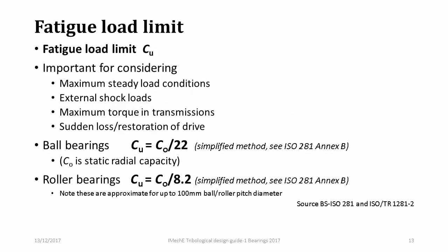Fatigue load limit. Even with all those calculations, we still have to be concerned about the absolute effect of load on the contact patches. So we have to consider a fatigue load limit. Now this is important if you're considering some very high steady loads or external shock loads, or the same thing said another way, the maximum torque in a transmission, or sudden loss and restoration of drive, for example if you're driving over very broken ground.